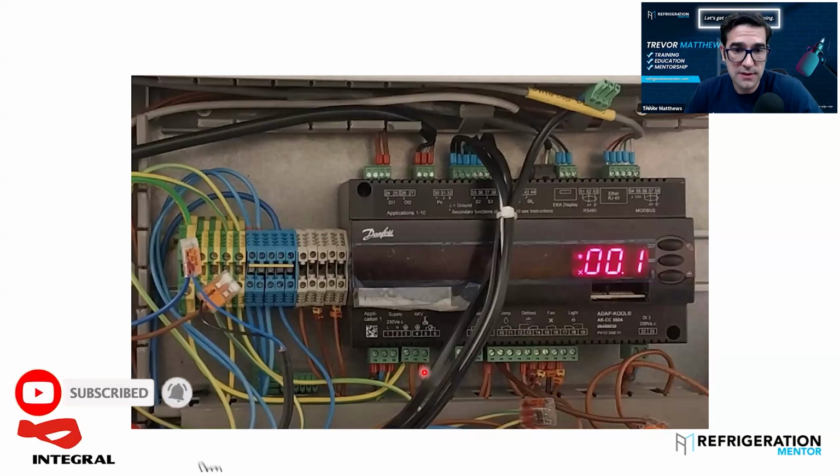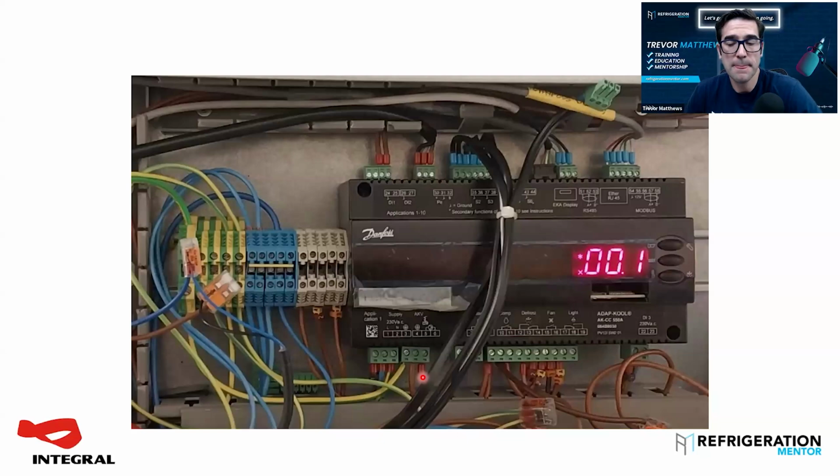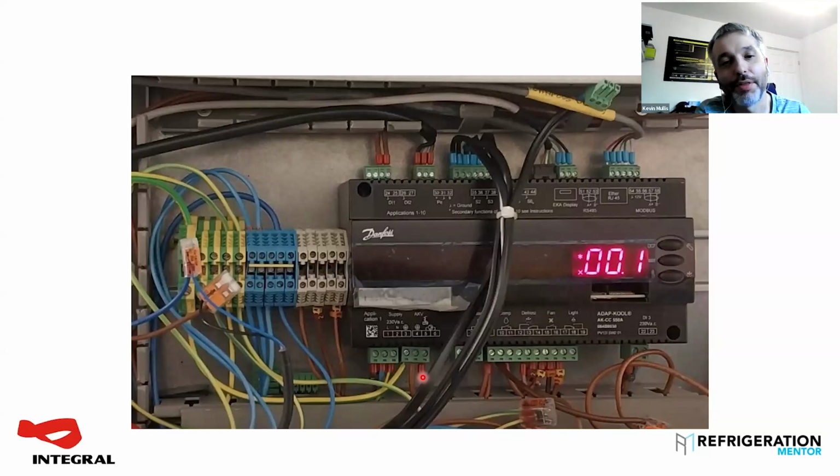Does that make sense? And that can totally happen because the coil plug, of course, has a rubber seal in it, but those rubber seals get old and hardened, or somebody doesn't do the gland up on the back of the plug, and it's very, very common to get rust in the plug, and that'll either rot the connection away and you'll get no connection, or you get a high resistance on it and it won't lift the valve. You won't generate enough to lift the valve. So that's super important. So that's if the controller thinks it's working and it's not, that is the most likely cause of you not getting any cooling. And it's the same for the other relays to the right of that.